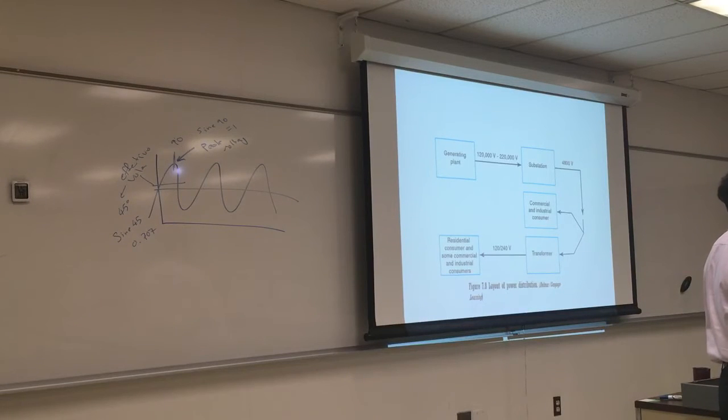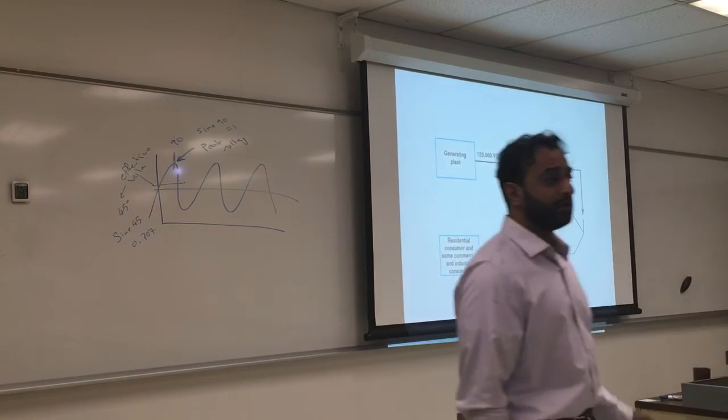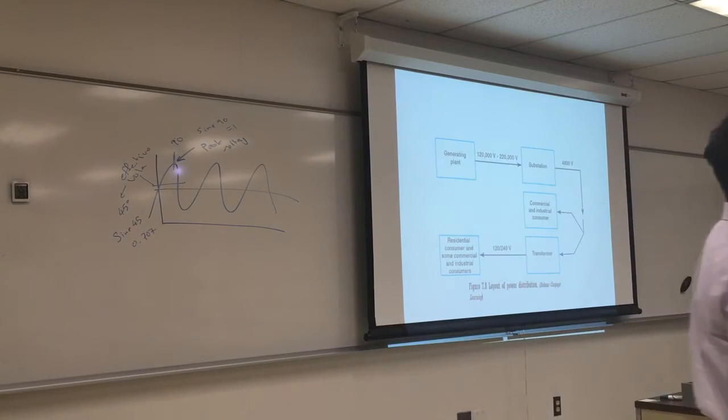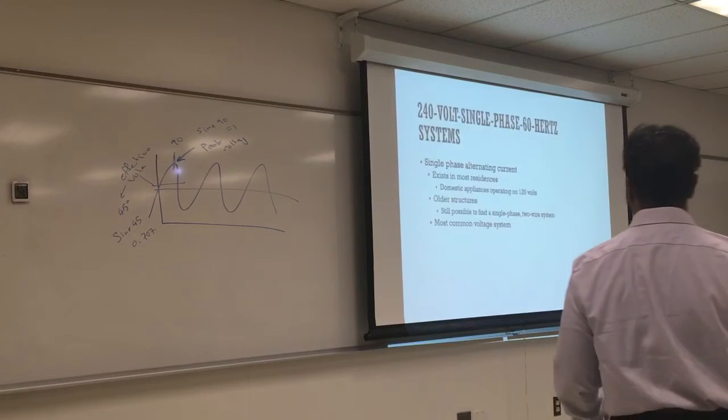If you go to a residential building, it has a different or funny looking control panel, and you have to wire your boiler. You want to recognize what it looks like and make sure it's familiar. If it's not, double check. Are you allowed to work on the control panel? Nope. Only a certified electrician. You're going to call somebody and verify.